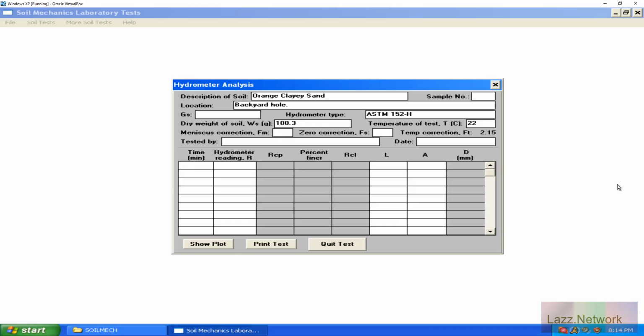Because your sodium hex is a particulate that is going to be in the water, it's really determining, with the sodium hex concentration that you're adding, how much is that offsetting your hydrometer reading? And then obviously temperature is going to affect how much it offsets your reading even more.